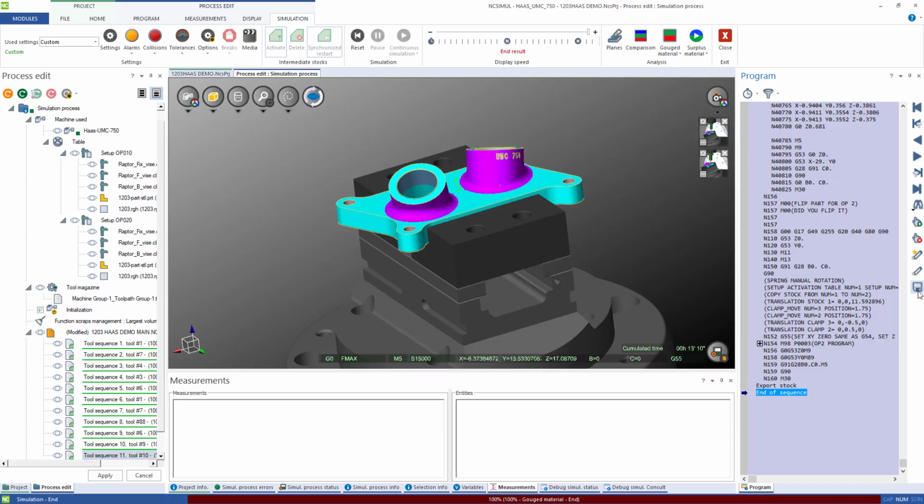So at that point, what you could do is come back down here to Save Program. And since it's again modified, I can just export this or output this as a save as basically. And you could decide whether to send that text file directly to the machinist on the shop floor through the network, or if you store them in some location where they're ready to go when the machine or the part is ready to be machined.